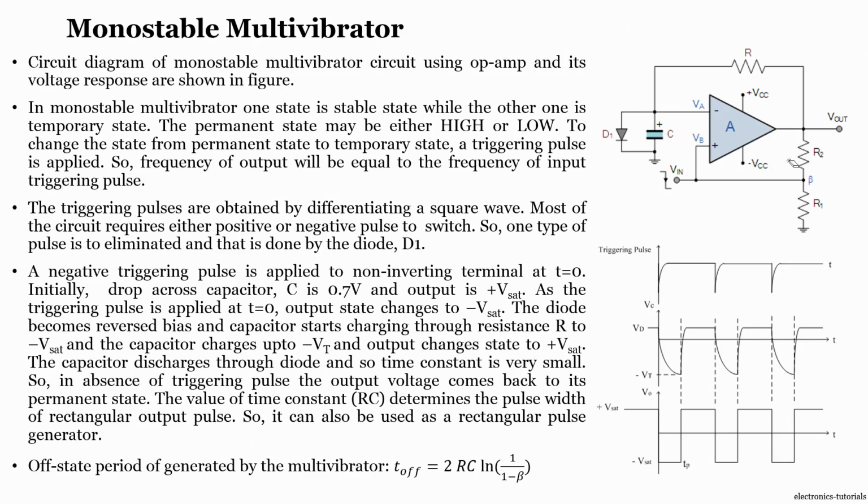That positive feedback means nothing but the resistors that we use in the positive feedback decide the value of beta, right. If we want to understand how exactly the circuit works, recall our previous astable multivibrator. We understood that because of the positive feedback, because it looks similar to our Schmitt trigger, it gives some thresholds, positive threshold and negative threshold. And since the output is connected to an RC filter, and the junction of RC is given to the negative input, when our input voltage is greater than the threshold, then it goes to either plus VCC or minus VCC based upon the input signal.